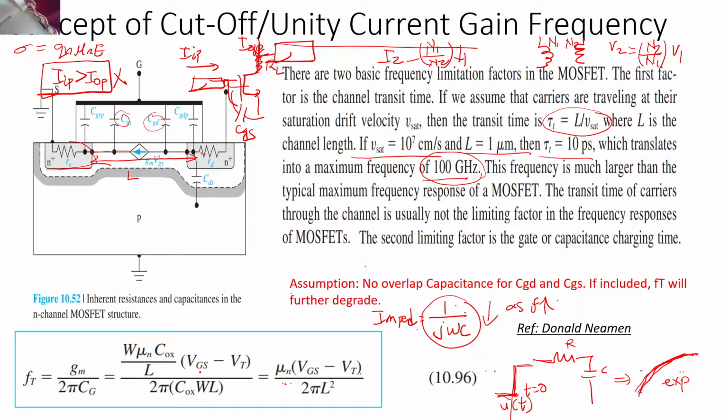This is basically a small change that you apply. So you have a DC that you apply to the MOSFET, and you apply some small voltage at the input of the MOSFET, at the gate, right? So that's how the AC plus DC works. You have a bias point and on top of that you apply some signal, right? It is that signal's frequency I'm talking about. So now this is the input current, this is your output current, right?